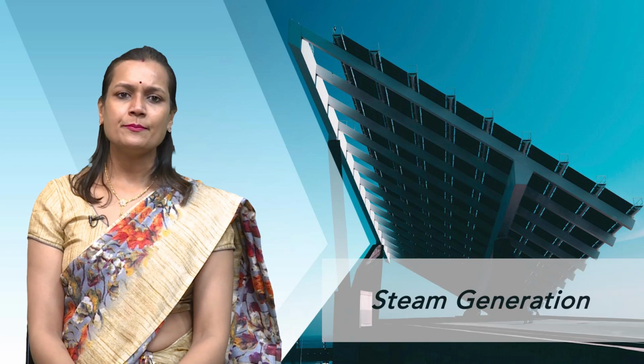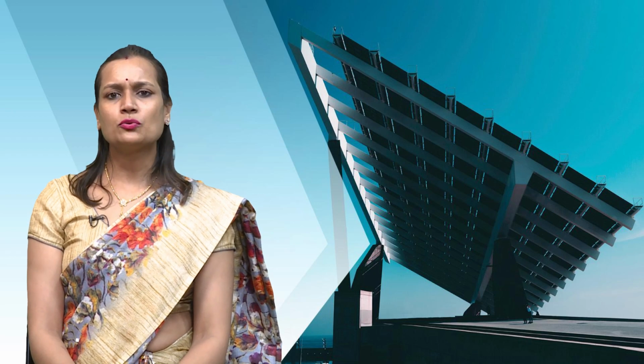In some power tower systems, the high temperature heat transfer fluid is used to generate steam. The steam can be used directly to drive a steam turbine or be used in a heat exchanger to generate high pressure steam for electricity production.